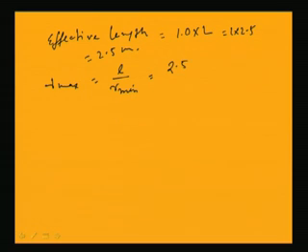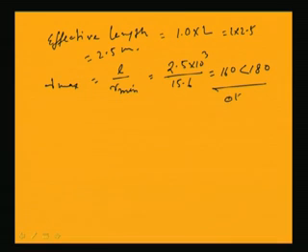So, 2.5 meter, I am making it millimeter, by r minimum is 15.6 for this section, that 80 by 80 by 6 angle section. So, this is coming 160, which is less than 180. So, from slenderness point of view, the section is okay.